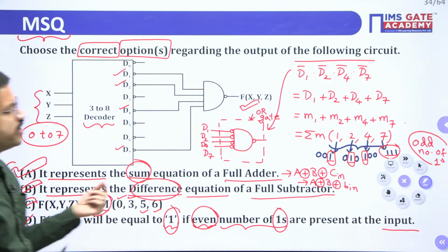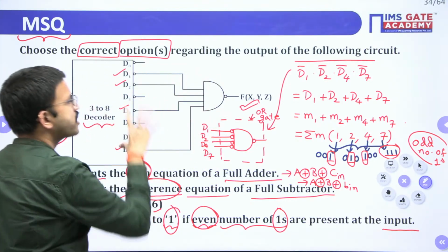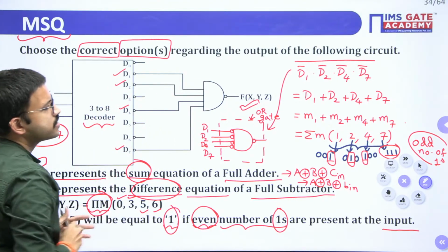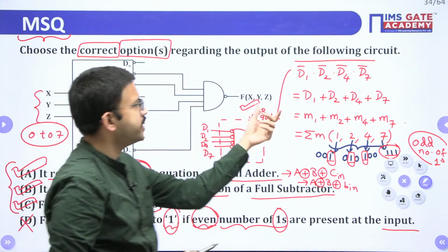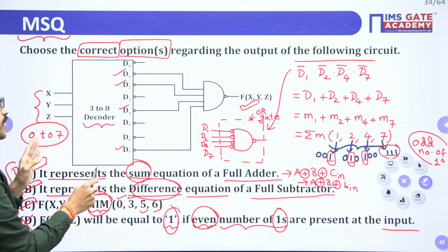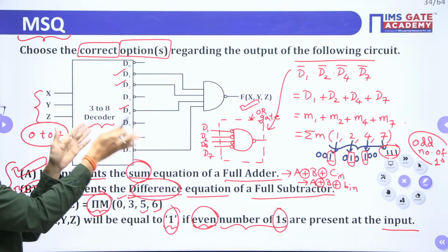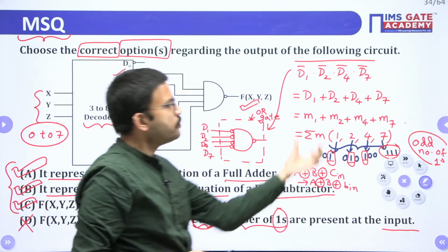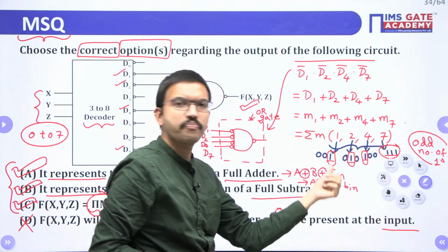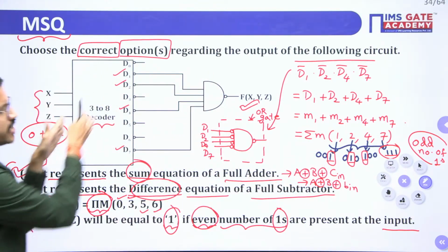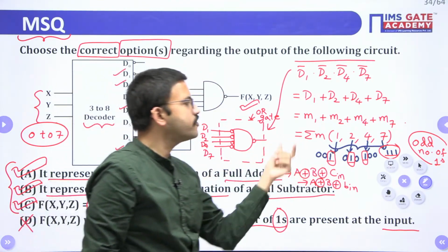Okay, see here, with the help of this question, you are having the decoder and some logic gate. Actually, they have given a NAND based circuit, but since you are having bubbles, I have just replaced this entire combination with a simple OR gate. Since the decoder will produce, sometimes they will give enable, sometimes they won't. If they give enable, when enable equal to 1, outputs of the decoder are nothing but minterms, right? Generalized case. So whatever the 4 input combinations you are having, you have to sum together. That means it is a sigma m form. So with the help of decoder and OR gate, you will get sigma m form, that means sum of minterms form.